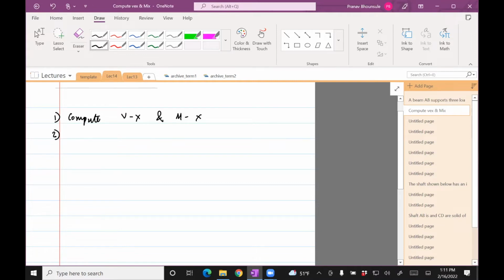Okay, then as I said, you could start off with one of those two criteria. Let's say we'll use sigma max to design for D and check if tau is less than tau max.